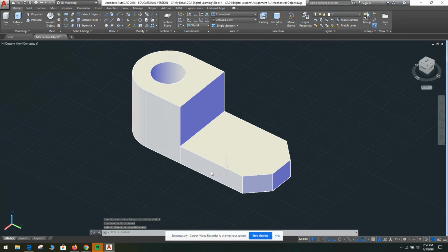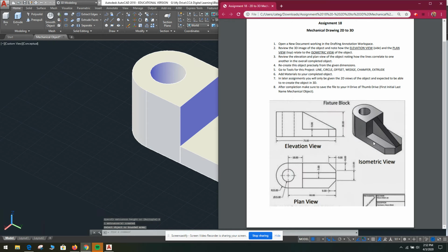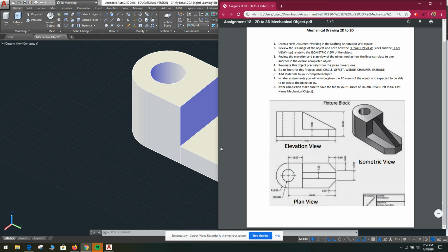Now, you may run into an issue where you press pull on the foot here, and it will not pull this one, or you'll press pull this one, it won't pull that one. It's because now it doesn't realize that you have a bottom line here that's demarking the boundary. So you may have to throw in a 2D line just to make sure that happens for you. If it doesn't happen, then you did it in the correct order and it's not confused. If you do it in a different order, you may have to throw in that 2D line. So don't forget about that.